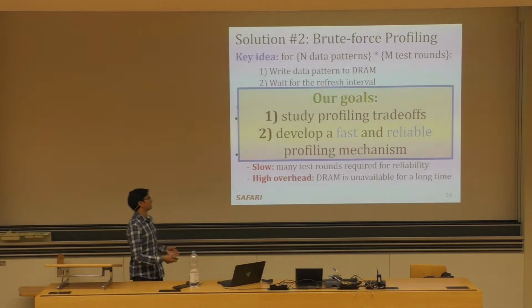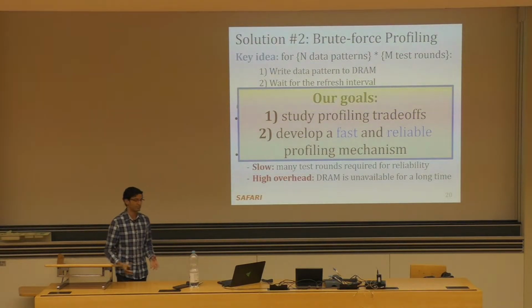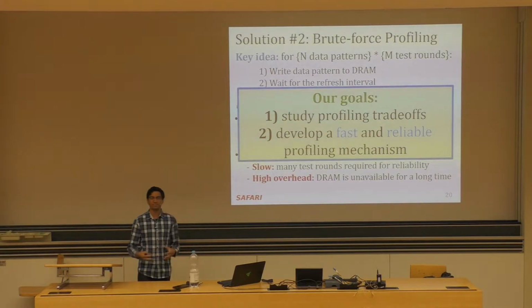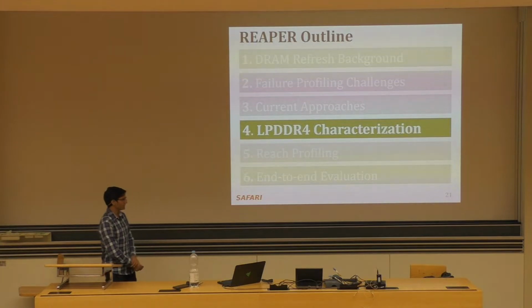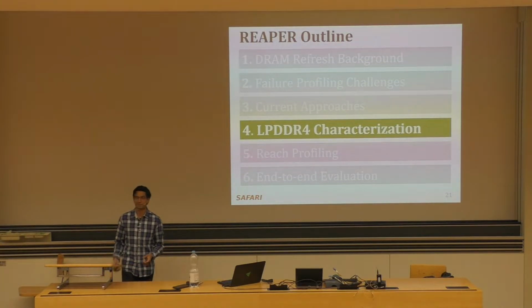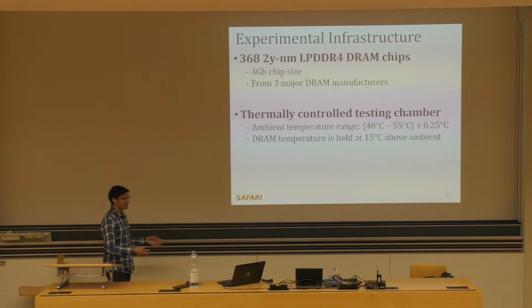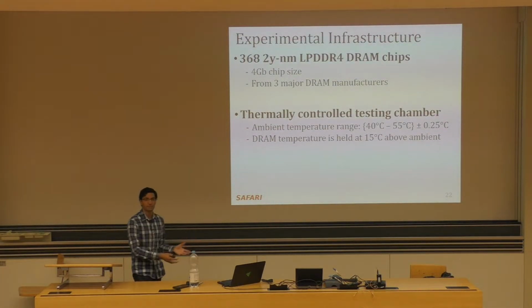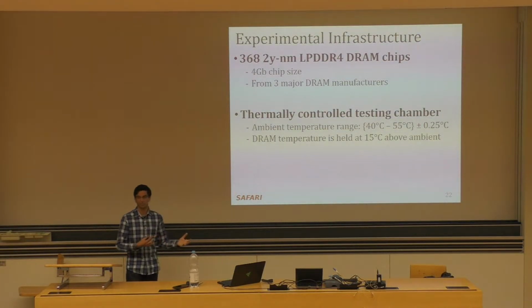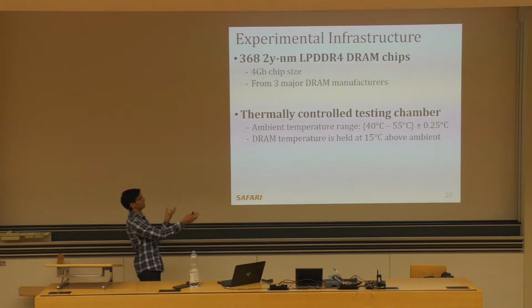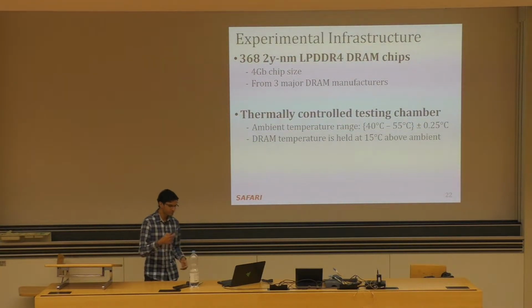Therefore, our goals in our work are to first study the different trade-offs surrounding retention failure profiling, and then develop a fast and reliable profiling mechanism to get around these issues. So now I'm going to talk a little bit about the characterization studies that we did with real devices, right? And so our experimental apparatus allowed us to test a whole bunch of LPDDR4 devices, which were state-of-the-art at the time this work was published. And we have devices from across 3 major manufacturers. And in order to isolate these temperature variation effects, we do all of our testing in a temperature-controlled chamber, right, which can test within a certain range and has some tolerance.